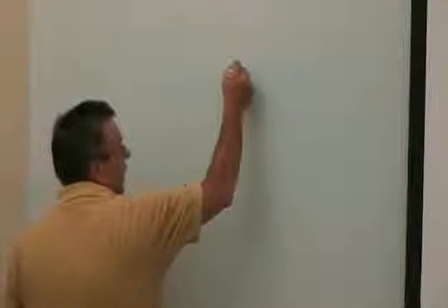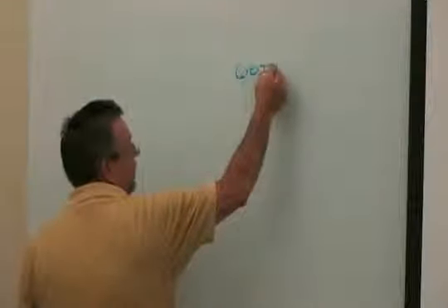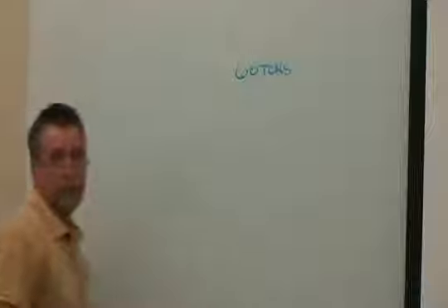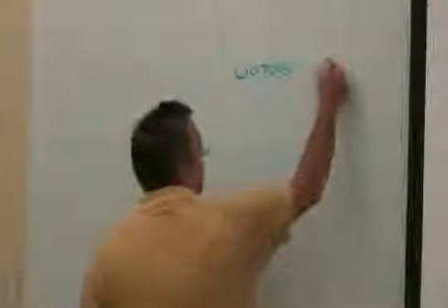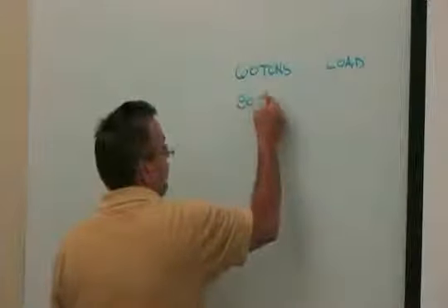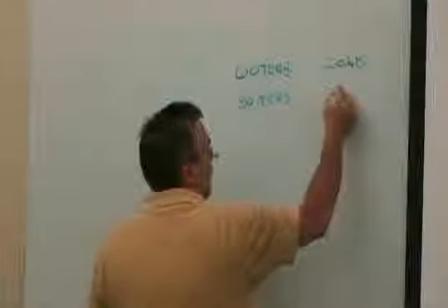We were talking about sizing, and we kind of left off last week with sizing of the boilers. But I've estimated my load at 60 tons for the building. But these are all incremental equipment. I've got a space here that requires 2.3 tons. I'm going to put a 3-ton heat pump, and it goes on and on and on. So my connected load might be 80 tons. Connected load.